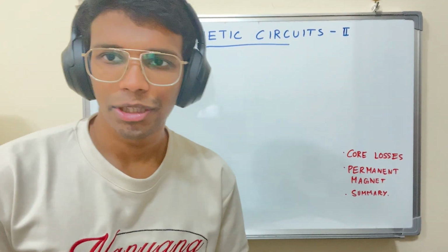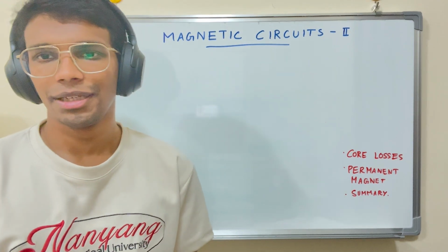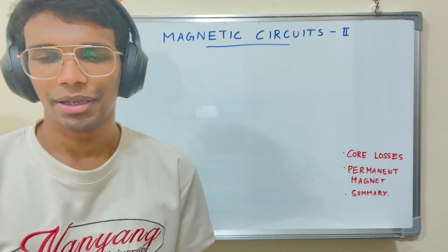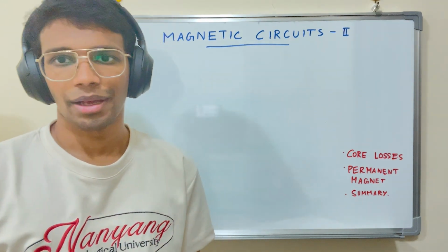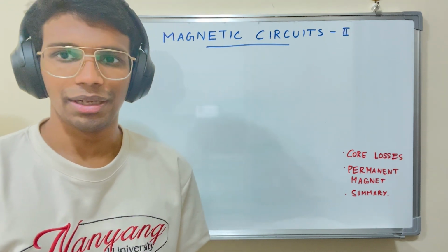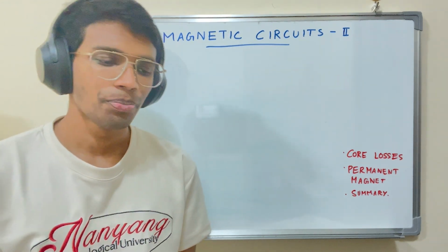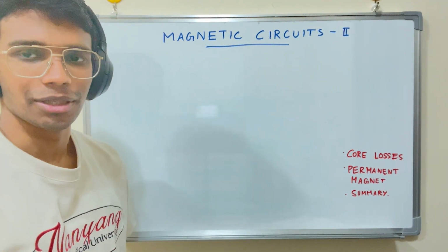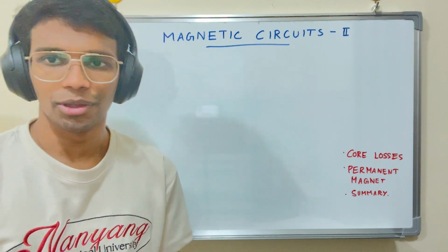In the previous equations we had the power loss as energy density times the frequency times the volume. Now that doesn't really say a lot unless the values of H and B are given, unless we could see the hysteresis loop. It's not a one size fits all. Since it's only for one cycle, we have to resort to an experimental formula, because it's not a linear function and it also follows hysteresis. It's not the same all the time. So we know that the loss is proportional or dependent on the area of the BH curve.